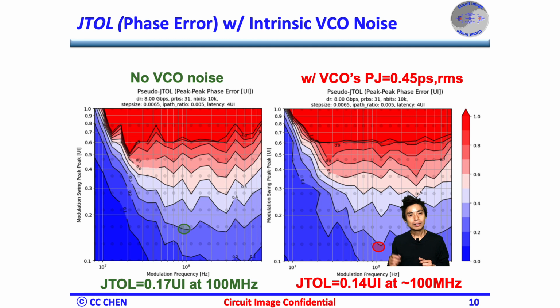On the other hand, we could also evaluate our system level power budget to see if the power number is realistic for power saving mode by making the VCO noise higher without corrupting the CDR's normal operation.